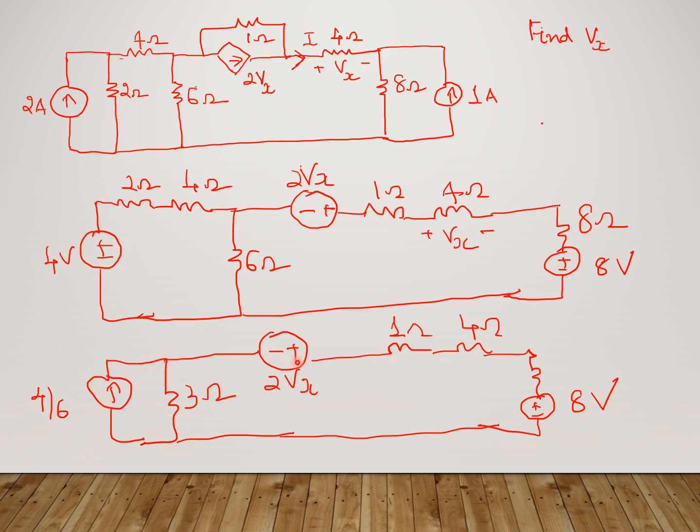So which means here you can see this is a voltage source, this is a voltage source. If I convert this also to a voltage source, we have an all voltage loop network. A simple KVL will, a simple series loop will come through which a current of I ampere is flowing. So it was already shown that the current through the 4 ohm is I, and the voltage across this is your Vx, which we are supposed to find out, right? So the next step would be to apply the source transformation over here and make this into one loop.